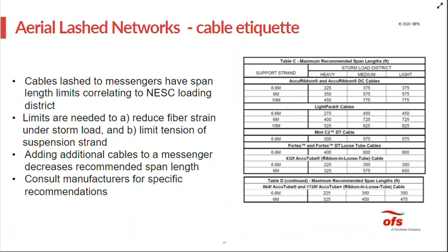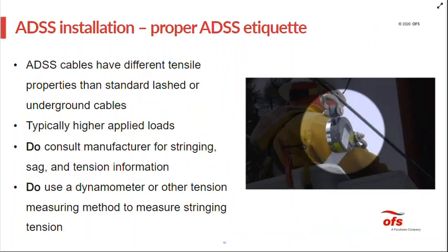And so, with that, different manufacturers may have different recommendations, so we'd recommend you contact your manufacturer. We have some recommendations placed on the screen, but contact manufacturers for specific recommendations. All dielectric self-supporting cables have different tensile properties than standard lashed cables or underground cables. These cables see their lowest tensions during installation, and they are designed to withstand the tensions of ice and wind, or both, long term.